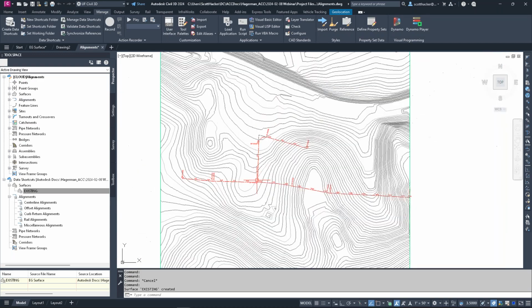There it is. That is in the proper location. I happen to know that. Again, I can't stress this enough: whenever you're referencing files, whether they are X references or data references, you want to be sure they're all in the cloud first before you start linking things together.